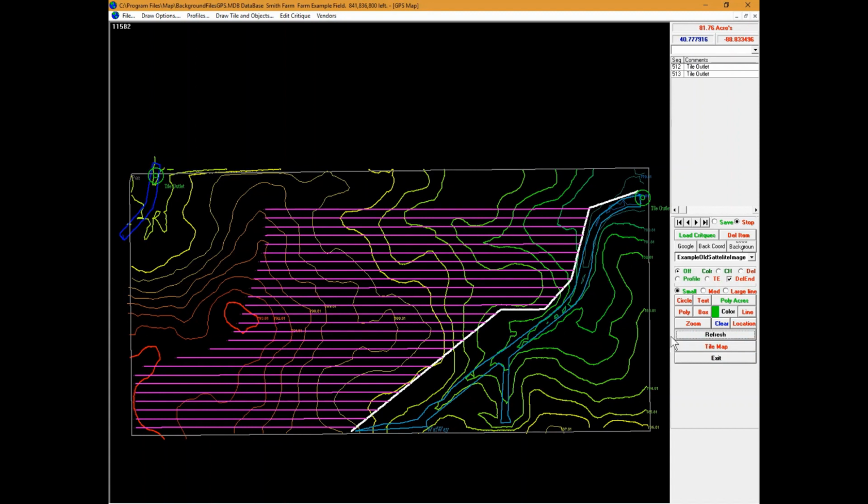In this case, if you look in the upper left-hand corner, we'll have our cursor over the main, and you can see that it has a grade, depth, and its number listed. You can then also measure your distance using the line measure tool, or simply just clicking and holding, and that way you can see what your distance is from the beginning of your main to a particular location. At this point, however, we only have profile information saved from the main.